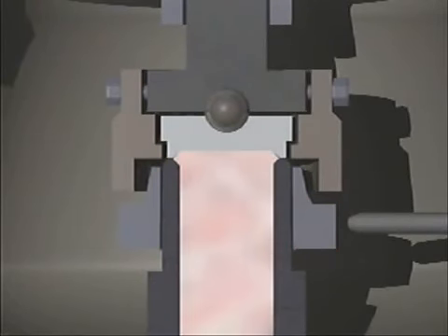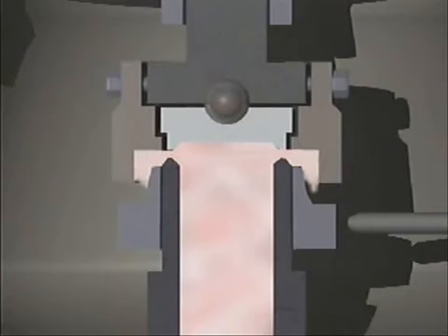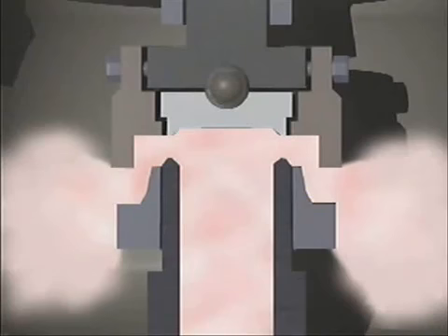The pressure of fluid directed against the disc lifts the disc off the seat. While the valve briefly simmers, the flow of the fluid as it discharges outside the valve's seating area increases the lifting force. Then, the reaction hood deflects the discharging fluid downward. Creating a reactive force by deflecting the flow of the fluid further increases the lifting force and causes the valve to pop open. As system pressure returns to normal, the valve closes.